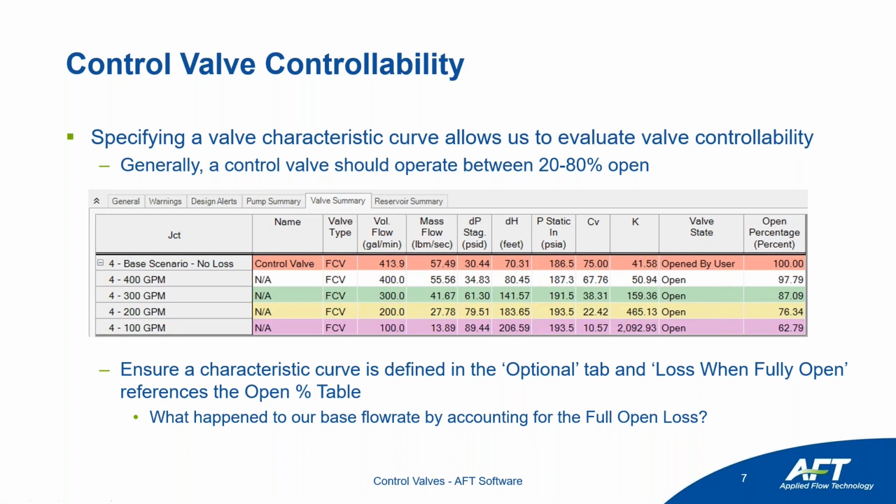So when we look at these quote unquote failure cases coming up, again, when the valve fails completely open, even if it can't achieve a volumetric flow rate, it's important to account for the loss that would be created by that component as well.